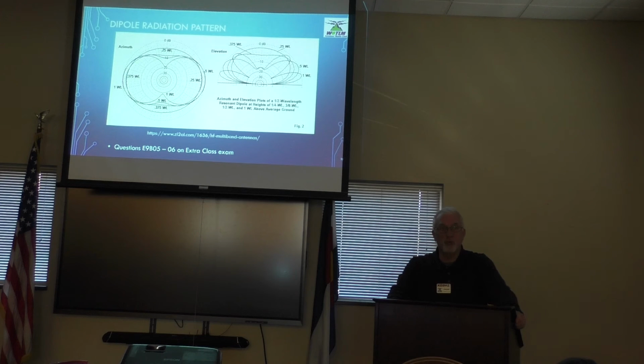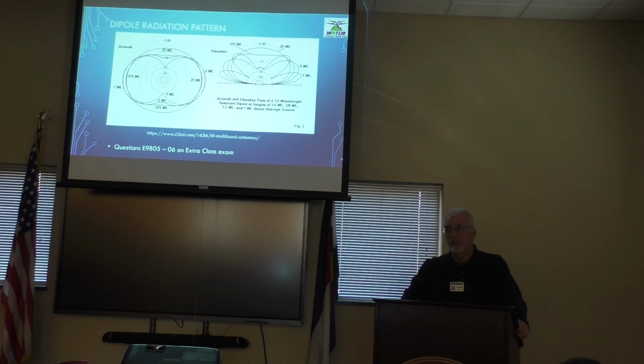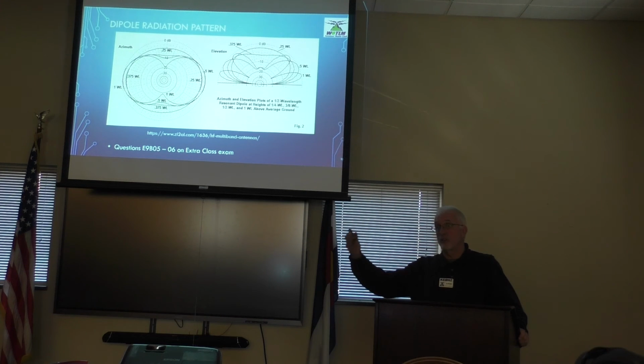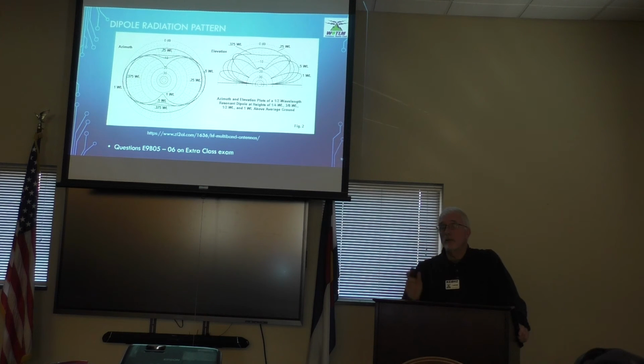Because it's really, really hard to explain. So think about this as general concepts, and your mileage will vary. Even identical antennas at different locations will have different effects because we've got different resistivity in the ground, presence of other buildings that cause reflections and interactions with all of this stuff. So when you're thinking about putting up a new antenna system, don't overthink it.